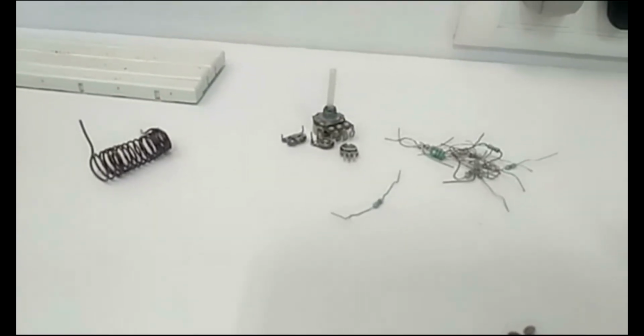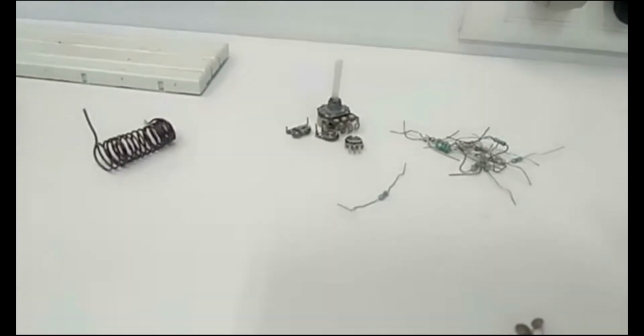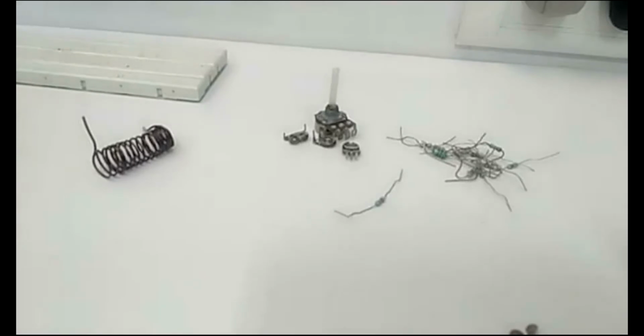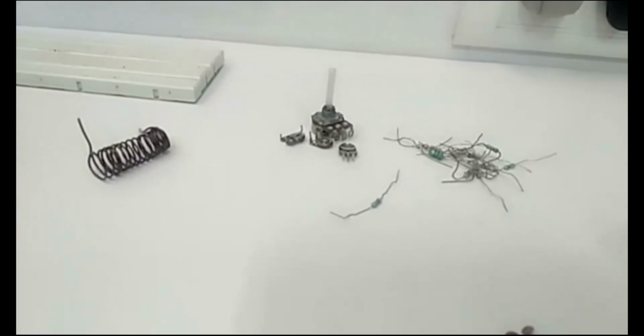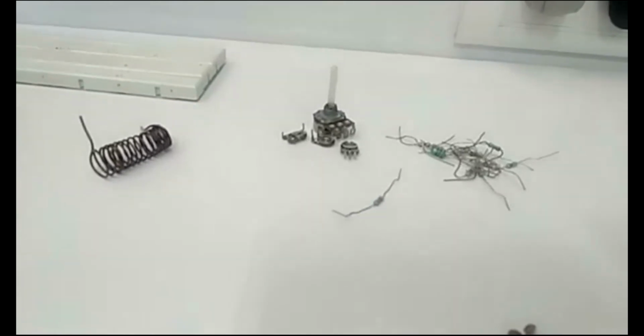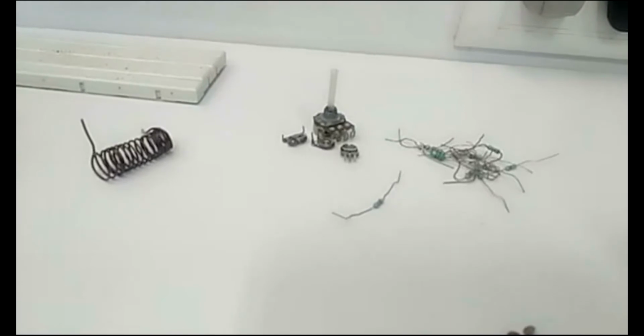So if we do not consider the tolerance band, then for this color code brown, black, and red, we'll have a resistor value of 10 times 10 to the power 2, or we can say 1000 ohm, or a 1K resistor. So in general,